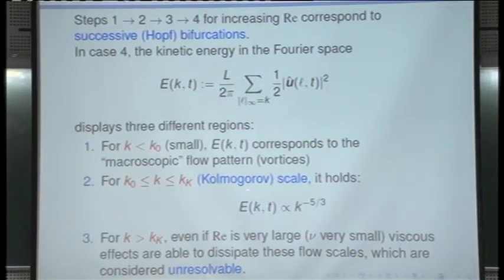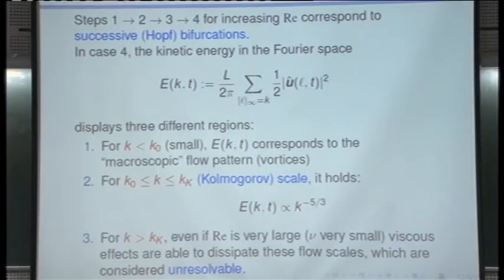Okay, in the analysis and simulation, also the numerical simulation of incompressible flows, it is very important to know that. Very important. This is the so-called Kolmogorov energy cascade. Energy has to decrease with a power of minus 5/3 in terms of the wave number. You have to keep that in mind every time you perform a numerical simulation of a turbulent flow.